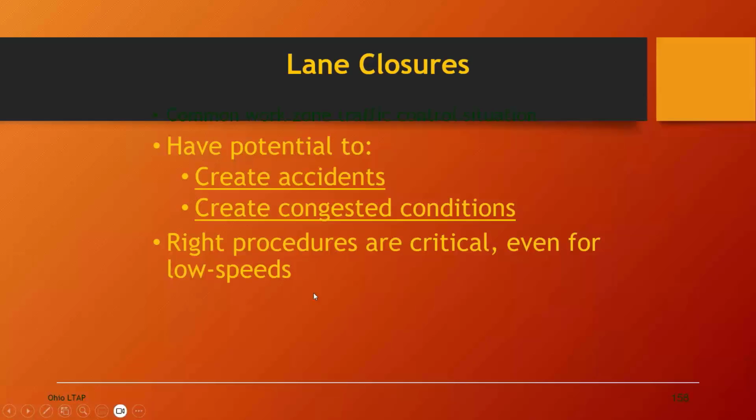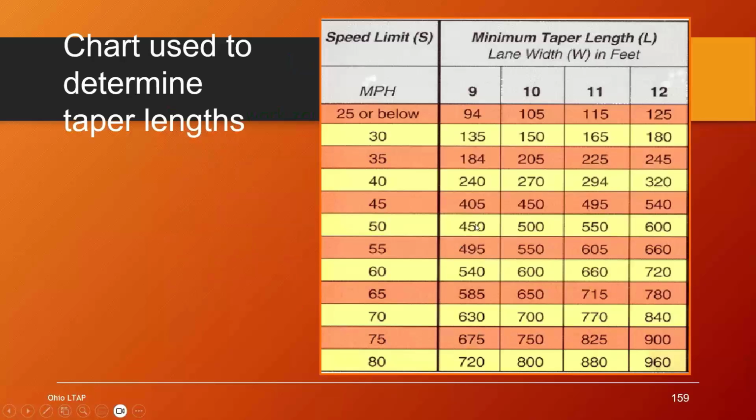And again, not just look at the picture, the illustration in that typical application. Read the notes page to see how else you can enhance the safety of that work zone, which might mention additional signs or making sure you have the proper buffer space. Another safety note is the buffer space. We're going to get to that next, so I'll save that for when we're talking about the buffer space.